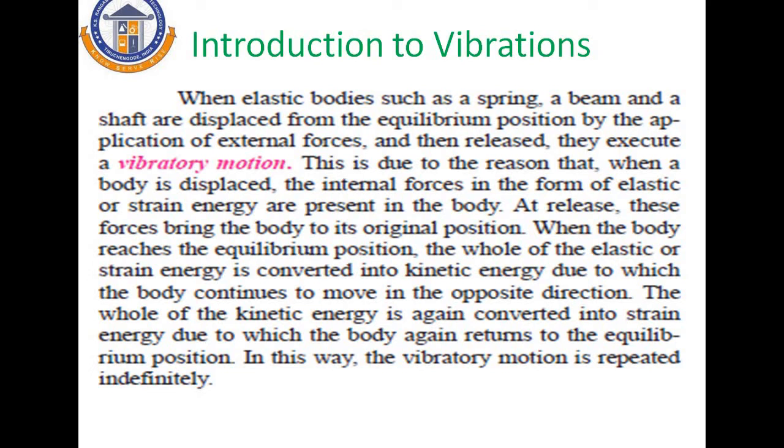When the body reaches the equilibrium position, the whole of the elastic or strain energy is converted into kinetic energy, due to which it continues to move in the opposite direction. The whole of the kinetic energy is converted into strain energy, due to which the body again returns to its original position. In this way, the vibratory motion is repeated indefinitely.